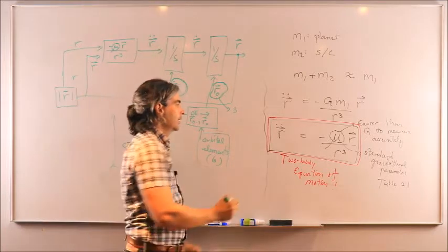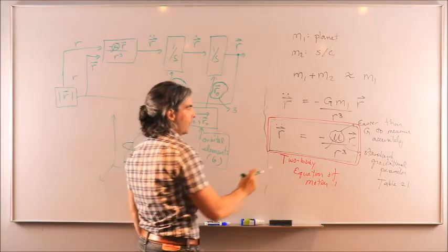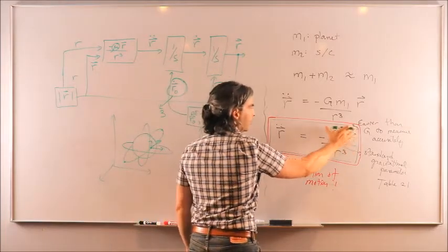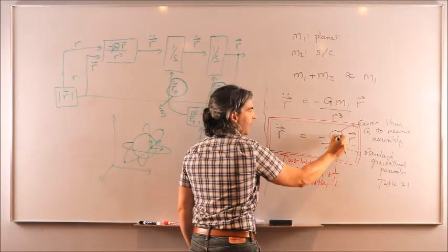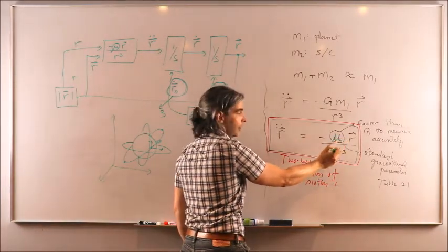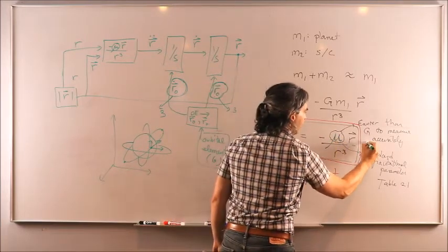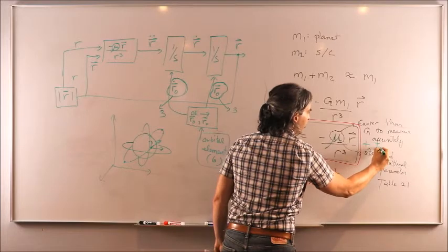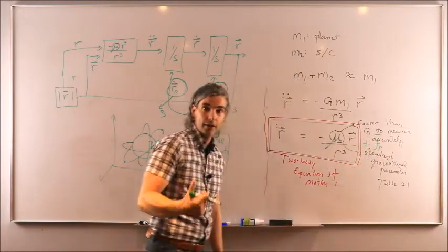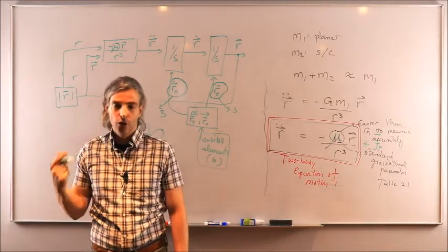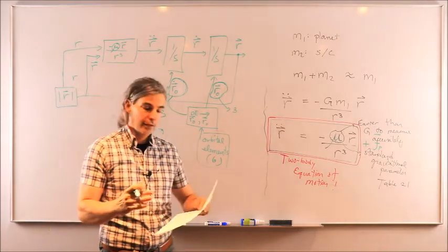And the reason why this is called the two-body equation of motion is because in practice, not only you have the gravitational attraction created by the planet on your spacecraft, and this is done through the mu parameter, but in practice you would also have additional perturbing acceleration, F_P vector, due to drag, due to solar radiation pressure, due to the non-sphericity of the Earth, right?